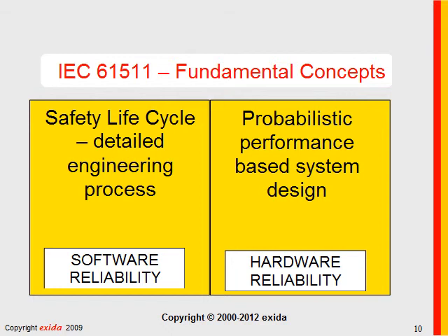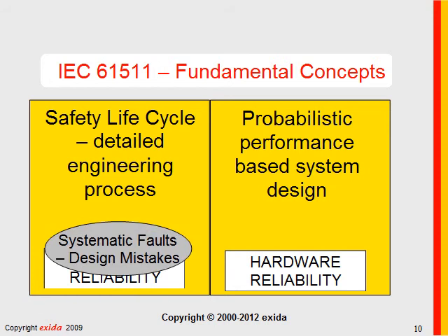Now, you probably remember the fact that IEC 61511 is based on two fundamental concepts. At Exida, we think of it as a detailed engineering process designed to prevent systematic failures or design mistakes, and a probabilistic performance-based system design allowing us to deal with sufficient safety integrity against random failures.